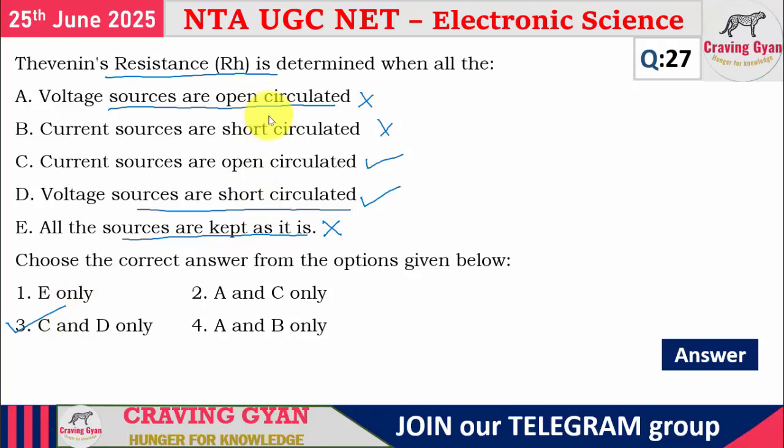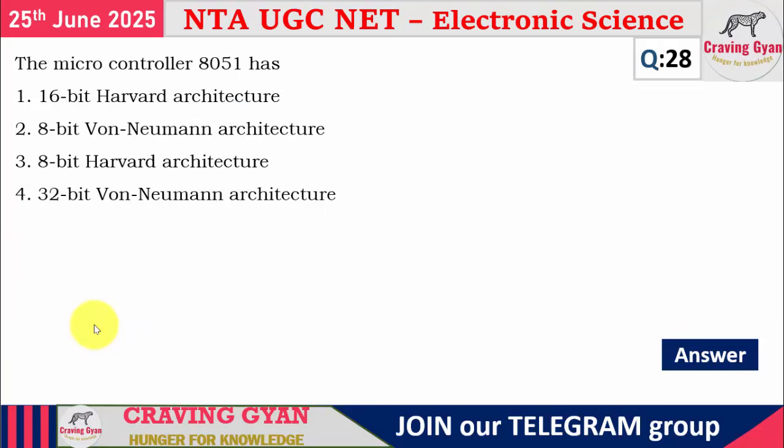Again I am going to tell, in order to find the Thevenin's resistance or Thevenin's impedance, all the voltage sources are short circuited and all the current sources are open circuited. Right? So C and D, nothing but option 3, is going to follow.